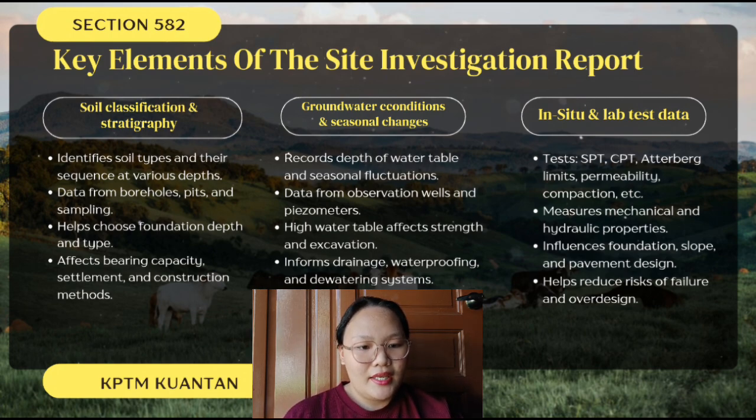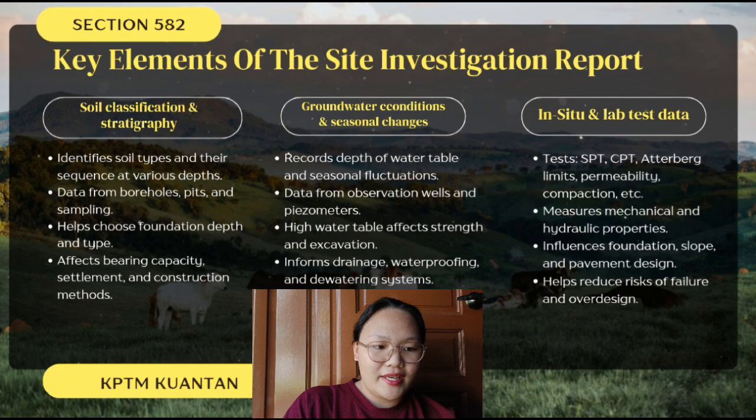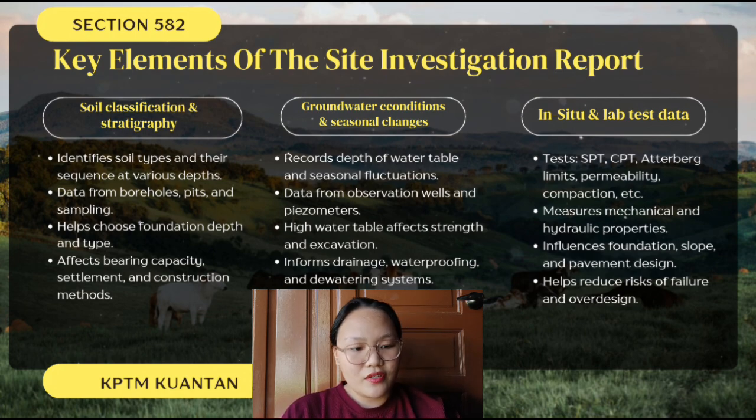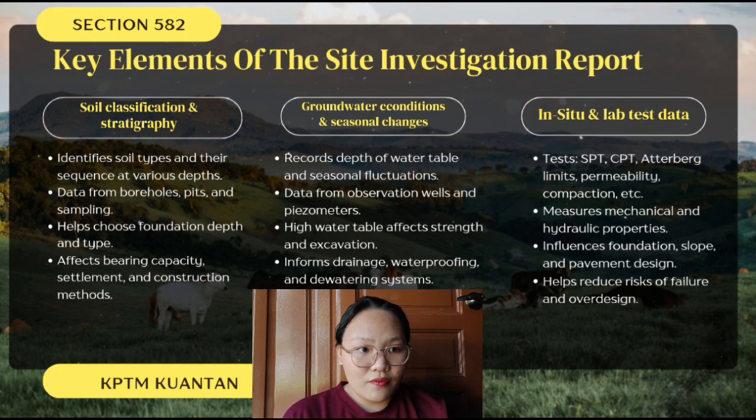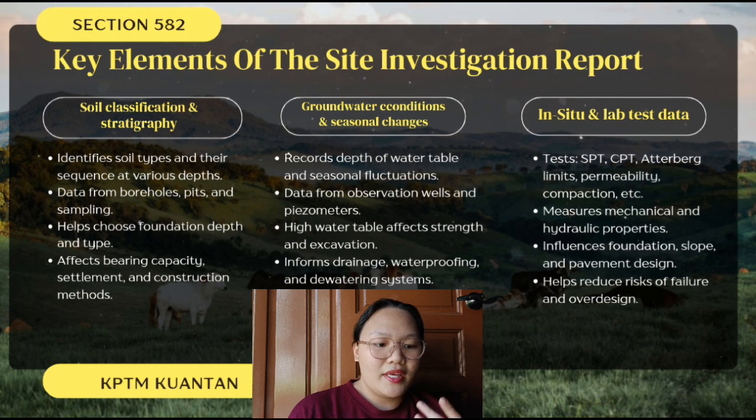Third is in situ and laboratory test data. These include tests like the standard penetration test, SPT, cone penetration test, CPT, Atterberg limits, and soil permeability. These tests measure how the soil behaves under pressure and moisture. The results are important for designing strong foundations, stable slopes, and long-lasting pavement. They also help reduce risk of failure or unnecessary over-design.